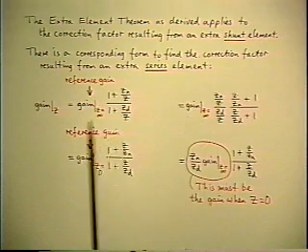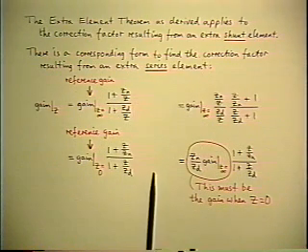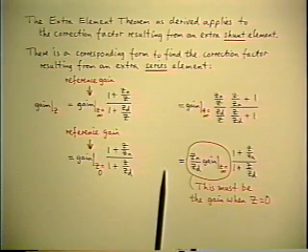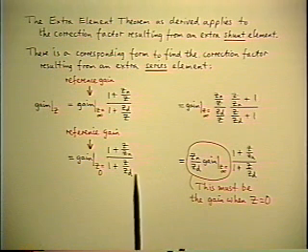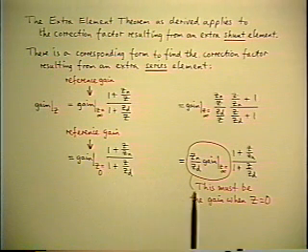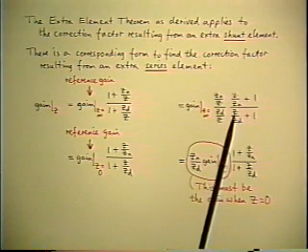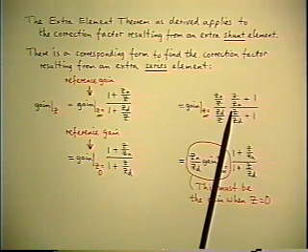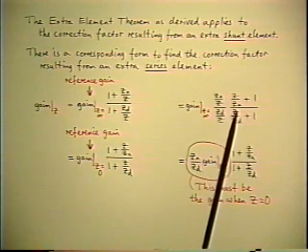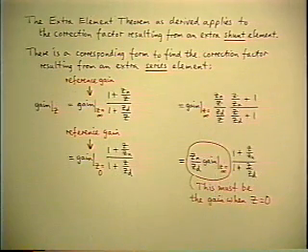Notice the analogy with this entire calculation with the frequency response of the gain in terms of 0 frequency reference and infinite frequency reference. The same thing. The only difference is the variable now is impedance instead of frequency. And instead of corner frequencies, you have driving point impedances. But the algebra is the same.